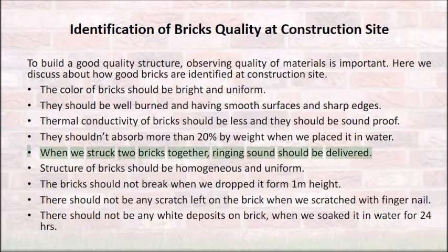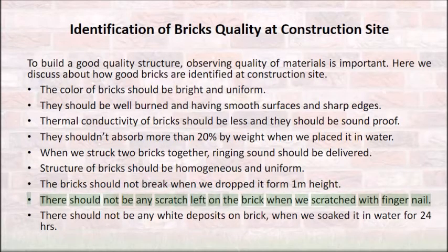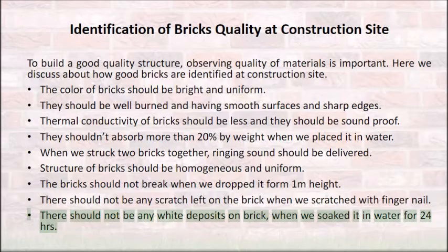When we strike two bricks together, a ringing sound should be produced. The structure of bricks should be homogeneous and uniform. The bricks should not break when dropped from a height. There should not be any scratch left on the brick when scratched with a fingernail. There should not be any white deposits on the brick when soaked in water for 24 hours.